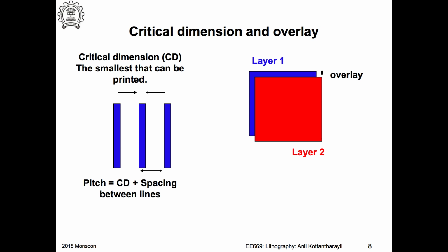Okay. So if you are doing a lithography process, and that leads to some deposition of particles on the wafer. Okay? So what would happen in the lithography process? During the exposure, for example, some particles fall on the wafer. What would happen? They will actually modify how much light goes in. Right? Because I have a photoresist and I am exposing this to light.